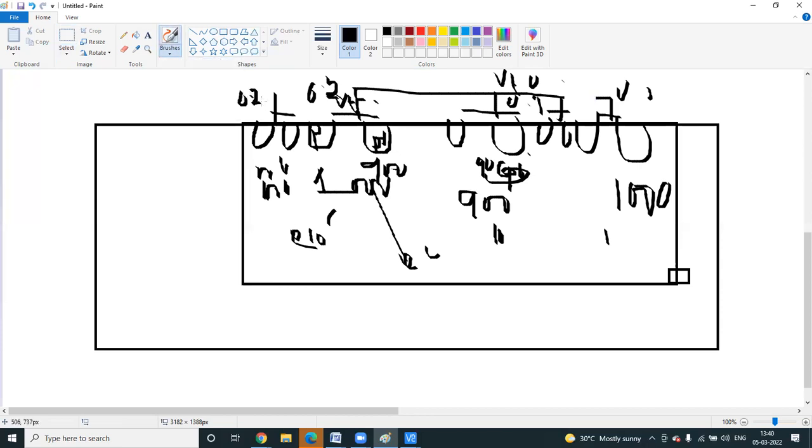At these end points Vt is 0.2, 0.2, and since they are dummy, no real operation will occur. And these three active devices will all have Vt of 0.1. Understand? Somebody asked me what is the use of dummy. To keep Vt uniform, we add dummies on the left and right side. This is the answer I want to tell. If any doubt, let me know.